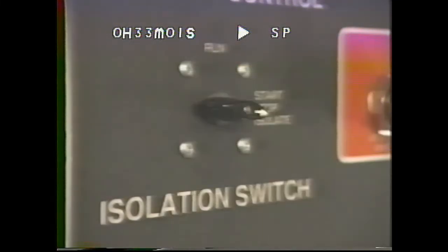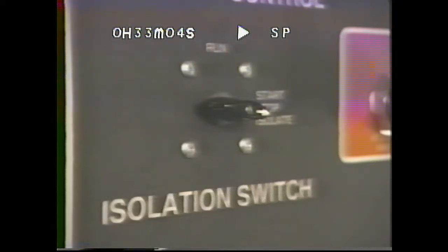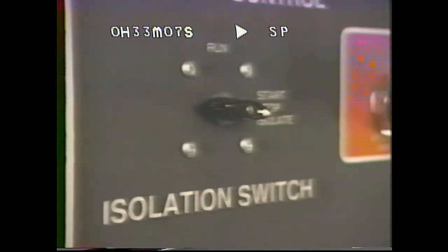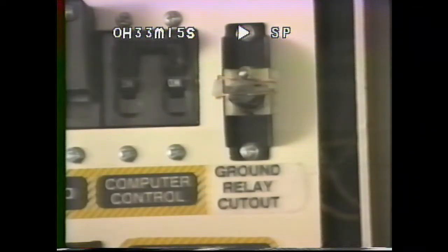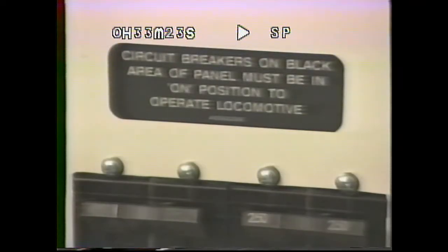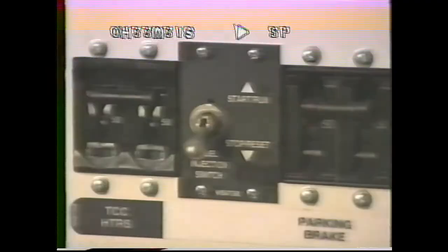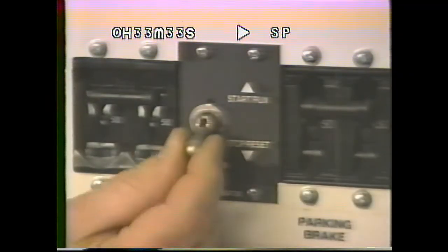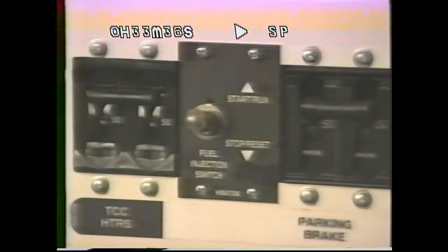Next, check the isolation switch on the engine control panel. Make sure it's in the start, stop, isolate position. Then, in the switch and circuit breaker cabinet, close the battery knife switch. Make sure the ground relay cutout switch is closed and that the auxiliary generator circuit breaker is on. Turn on all the circuit breakers in the black area, as well as the turbo and computer control circuit breakers. Then, place the fuel injection switch in the run position. Now you're ready to start the engine.